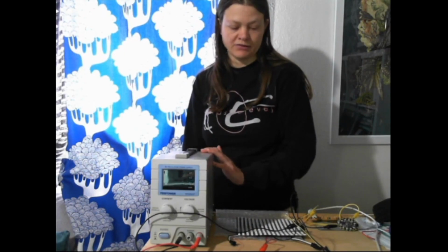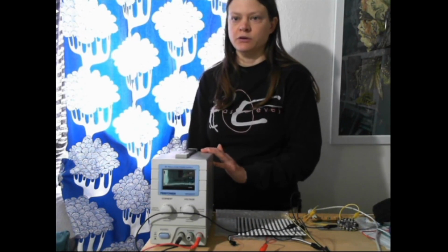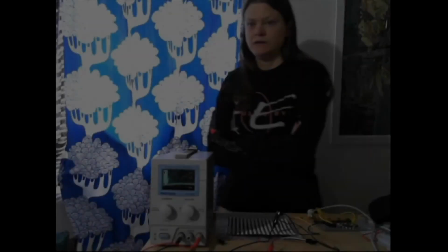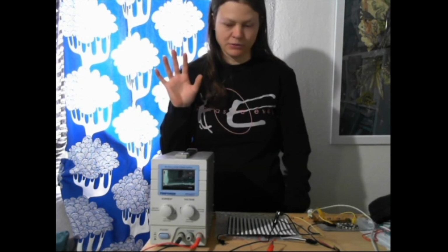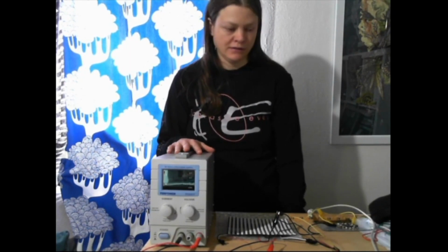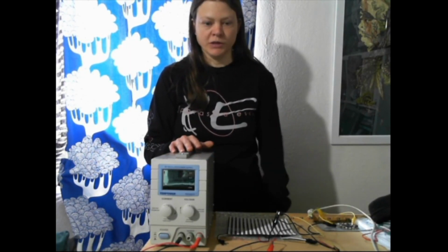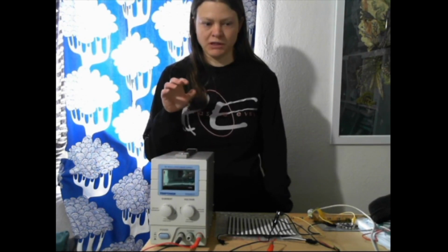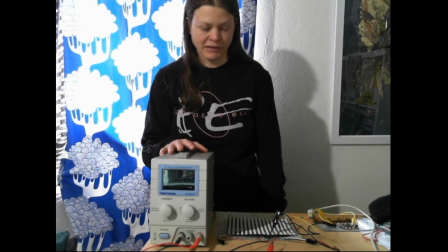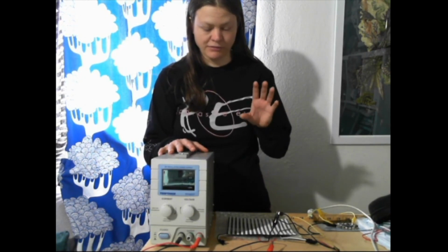Cool, so now we're ready to turn it on. I'm going to go upload code and come on back. Okay, and here we are. I've uploaded code and I'm ready to turn this on. The first thing we're going to do is power up the power supply. It's no big deal this time because we're not powering anything off the board, but if you are, you really want your power supply on first so that there'll be enough power for whatever lights you have plugged in.